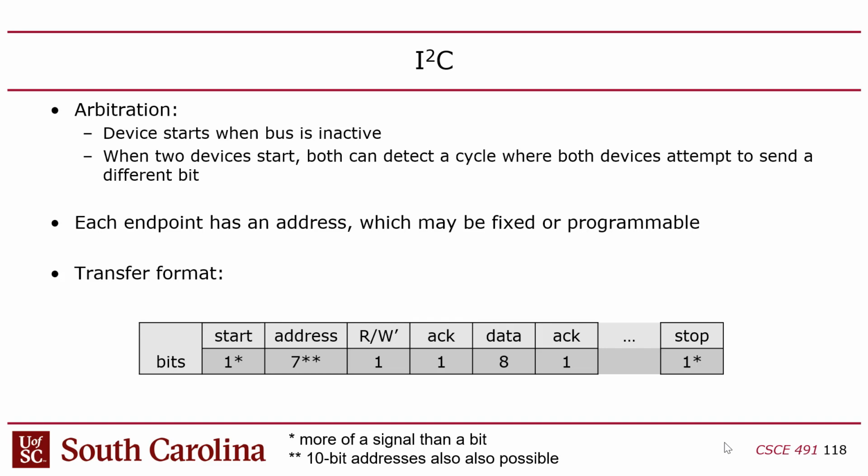that address. Because the idea is that you're going to have multiple potential masters and slaves hanging onto that bus, and everyone's going to have an address. And so when you send out this address, what you're really doing is calling out to some endpoint that has that address. And if that endpoint is there, it's going to acknowledge that address, and you'll know he's there. If he's not there, then there's no point in continuing. You're like, no one's listening to me. Apparently that peripheral dropped off the bus, right?